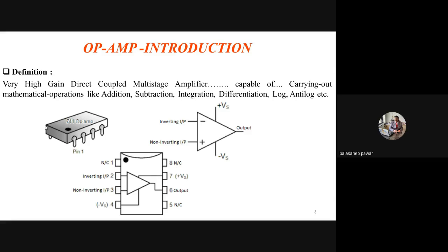You already did it. The achieved gain was 30, if you can recall, 30. Am I right? 3 volt was the output peak to peak voltage, and input we considered as 100 millivolt peak to peak, right? So the calculated gain for that CS MOSFET amplifier was 30.